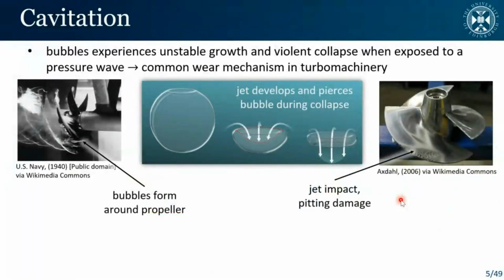Now, more specifically, I'm interested in cavitation. This is the phenomenon where bubbles can experience unstable growth and then violent collapse in response to a pressure wave. I like to think of cavitation as the flip side to boiling. In boiling, we increase temperature until we start getting vapor bubbles forming at the surface. In cavitation, instead of raising the temperature, we drop the pressure in our solution. That might seem a rather trivial distinction, but it actually has quite big implications in engineering.